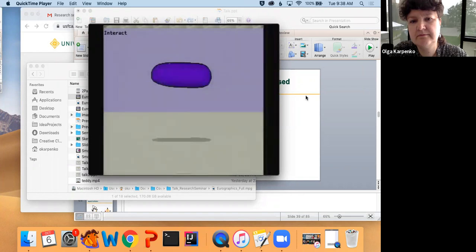The third operation is modification. The user can make small modifications to the shape of the blob by drawing a stroke near the blob's silhouette. This removes some of the constraints that define the implicit representation, but adds others. The surface adjusts itself to meet the new constraints.